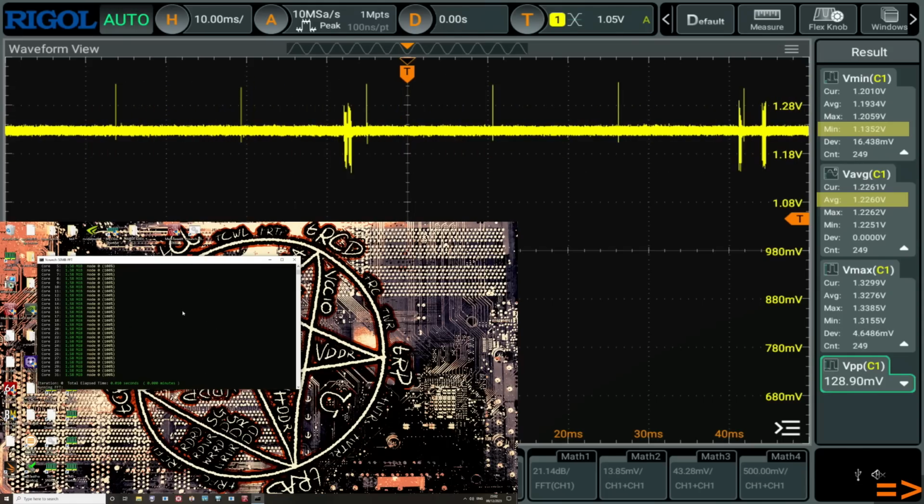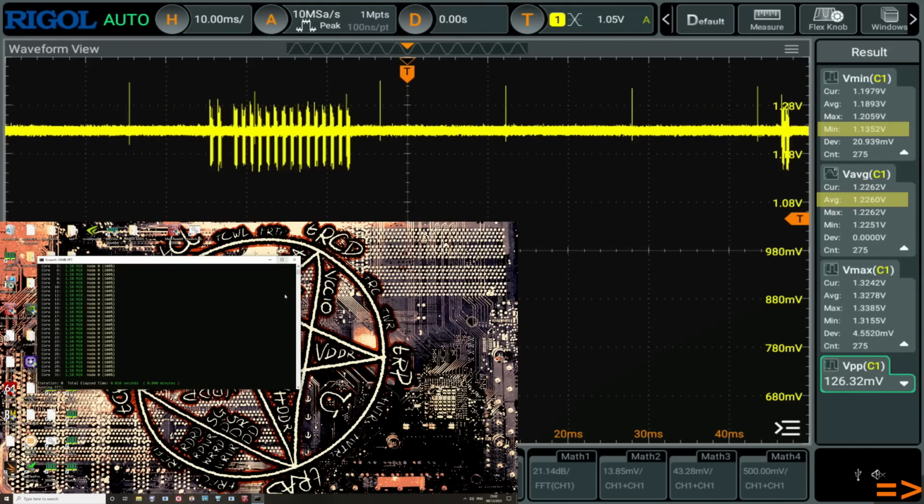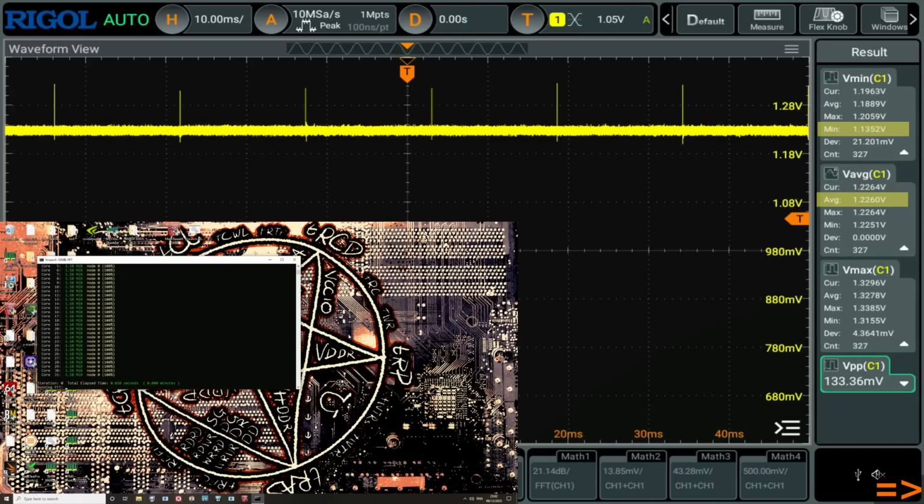And if I move the mouse, we start hitting 1.13 volts. So we see about a 20 millivolt improvement compared to mode 1, which is actually kind of disappointing. You would think a 40 millivolt increase in V-droop would lead to a roughly 40 millivolt reduction in undershoot, but we're not even seeing that. So yeah, mode 5 is also just completely terrible.